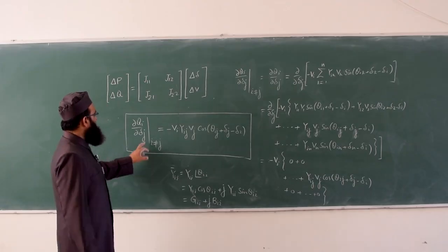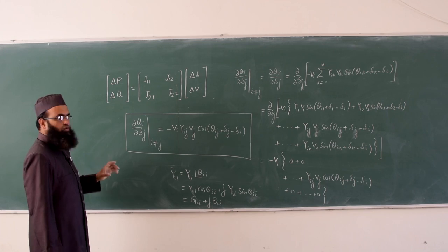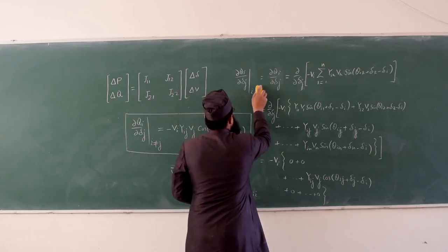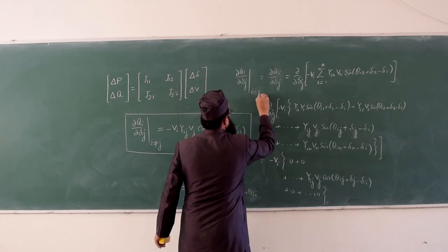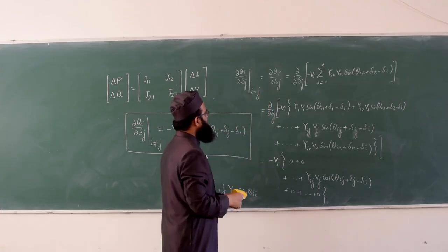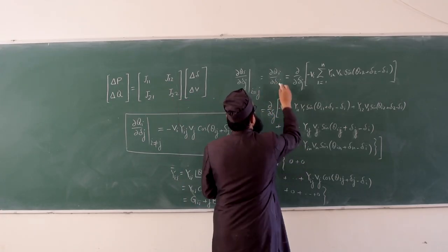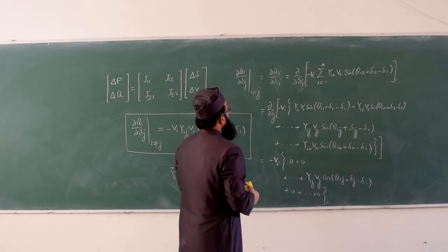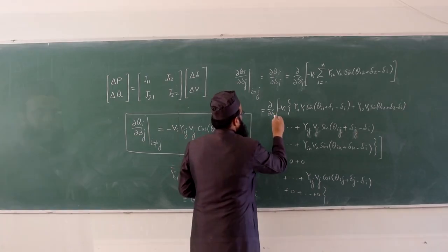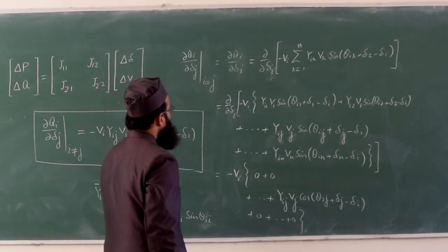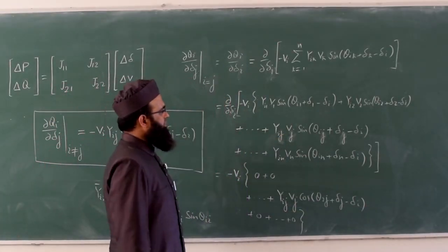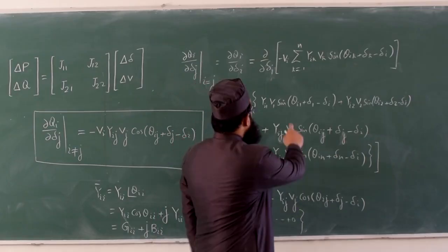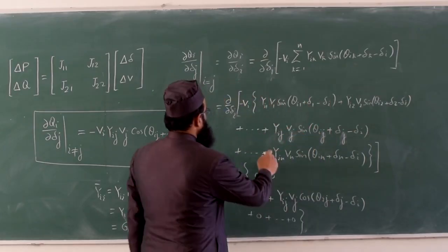So, the next, when I is equal to j means del Q2 upon del delta 2 or del Q3 upon del delta 3 and so on, for I is equal to j, right here del Qi upon del delta j for I is equal to j, we may write this will be del delta I. So, instead of jth term we will focus on ith term, and here we will write I. So, wherever j is there we will write I, because we have to focus on ith term this time for delta I. So, first term, second term and ith term.